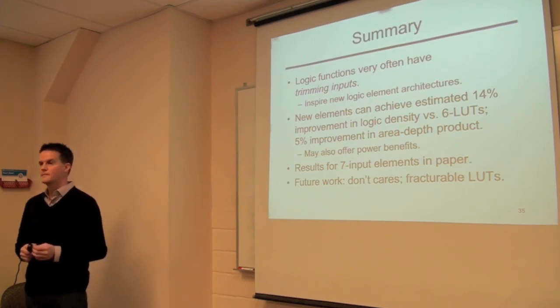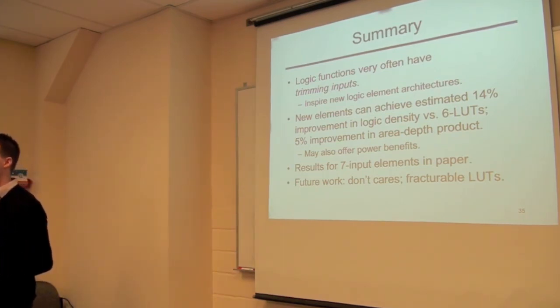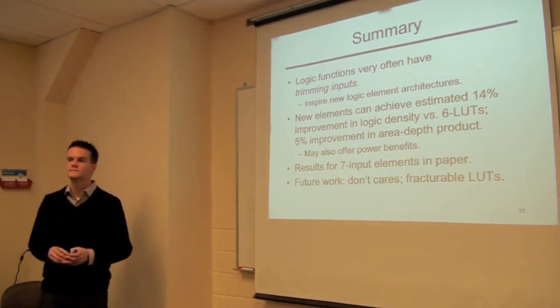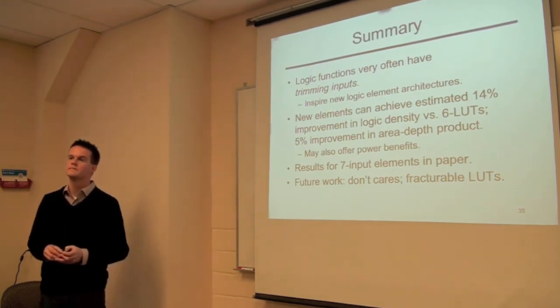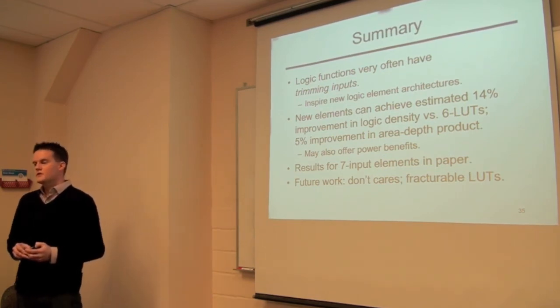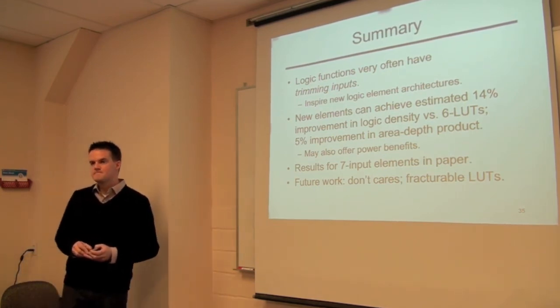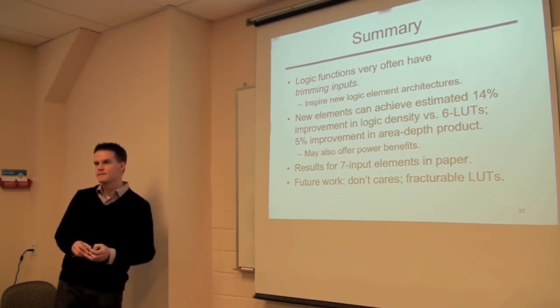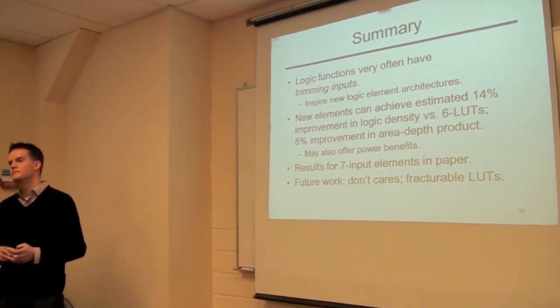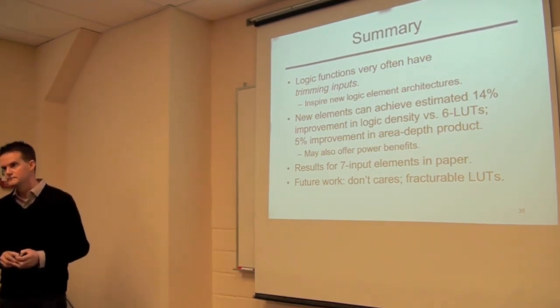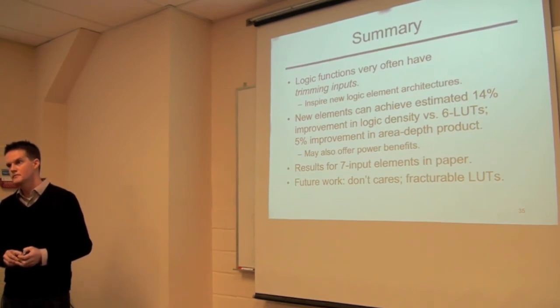Greg? So I guess a power question. When you're doing mapping, do you think your choice of cofactor bit would have a significant impact on dynamic power? Okay, in what sense, I guess? Well, the cofactor bit is choosing one part of the circuit or the other. So if you chose a bit that happens to switch a lot versus one that doesn't, it seems like that might have more or less of an impact on dynamic power.